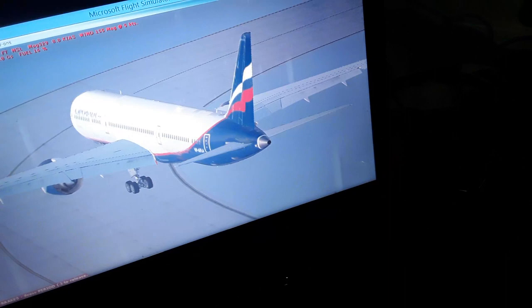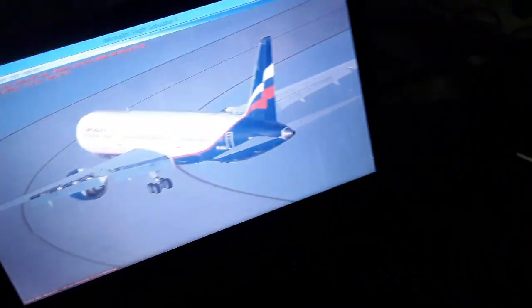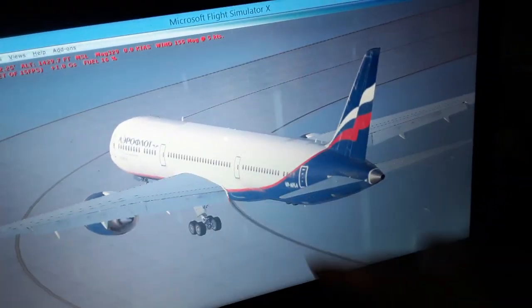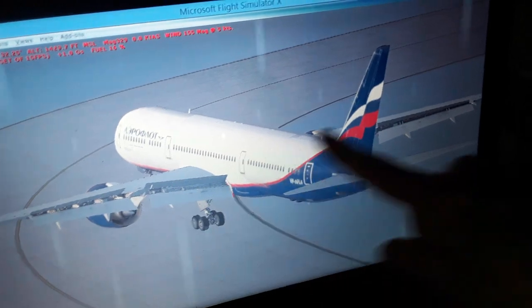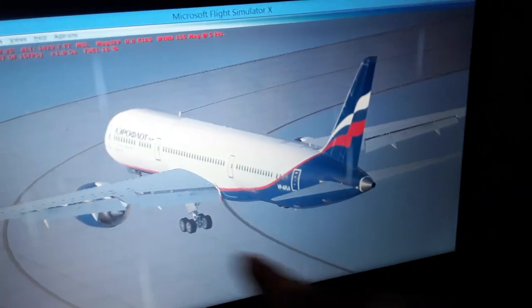We make the aircraft roll in flight. You can also apply the elevator to climb or descend, keep you level, and the rudder. So you roll left, right with the side stick in the Airbus, ailerons and spoilers. Left side stick, you can see ailerons here and spoilers over here. Also spoilers extended, and in the Boeing we have the flaperons. Down here we have the flaps fully extended, like this. So it's easy to remember.